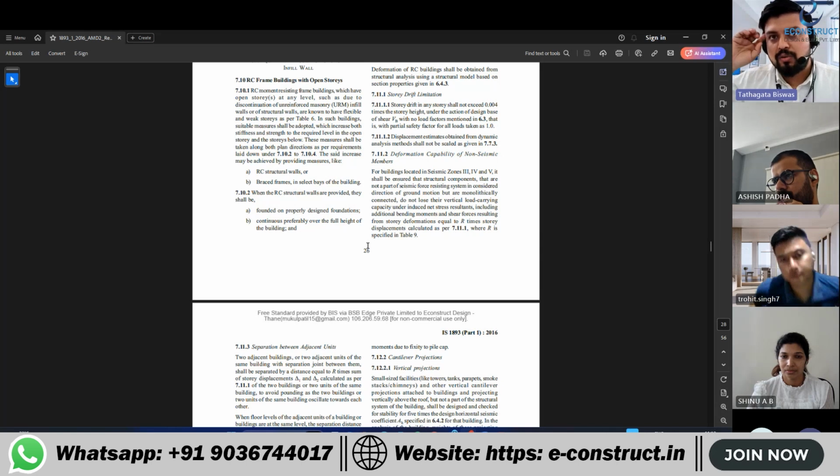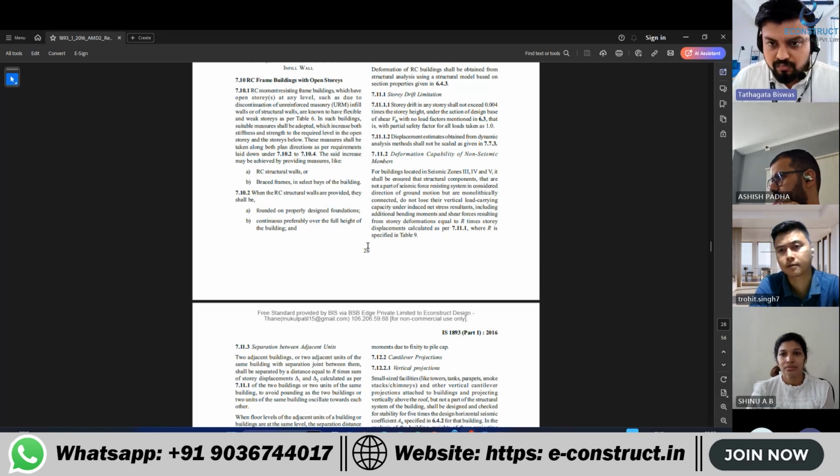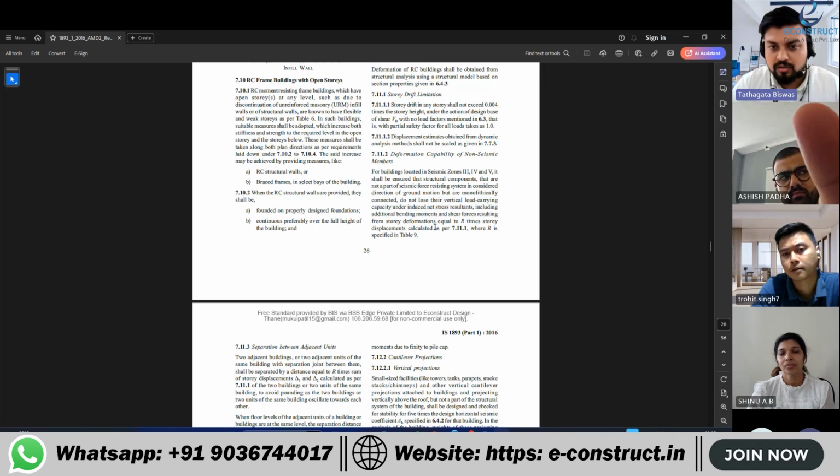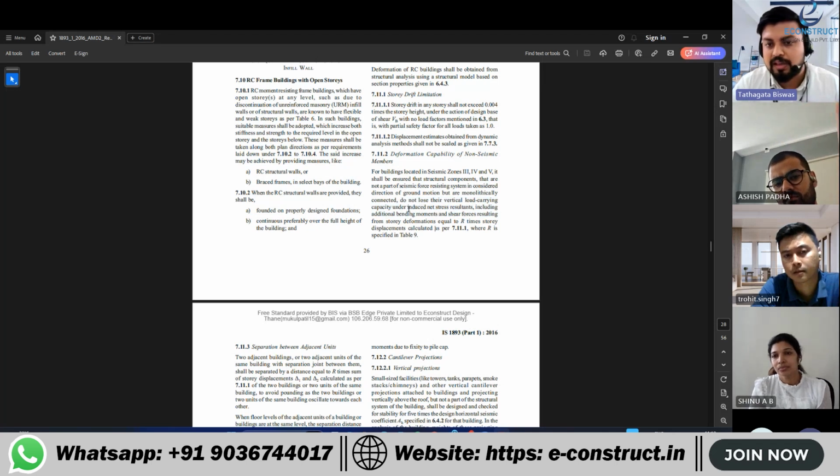So whatever you are doing as non-ductile or non-seismic elements, in case of, let's say, a structural wall system, if there are any columns, then that column moment you also need to distribute to some other elements so that it should be out of danger.